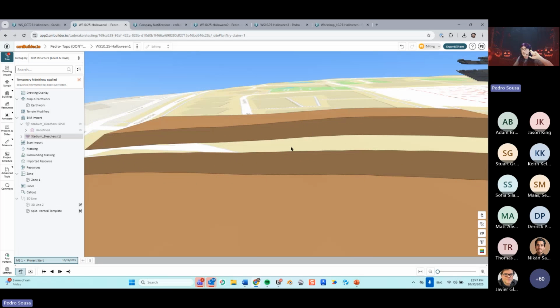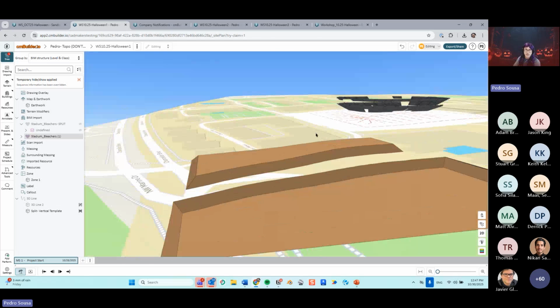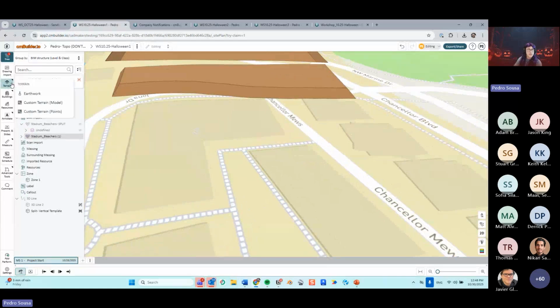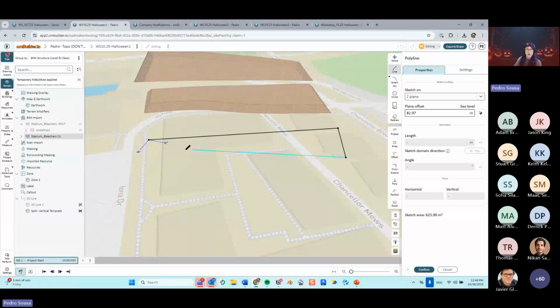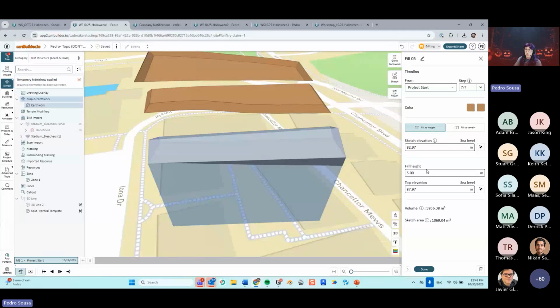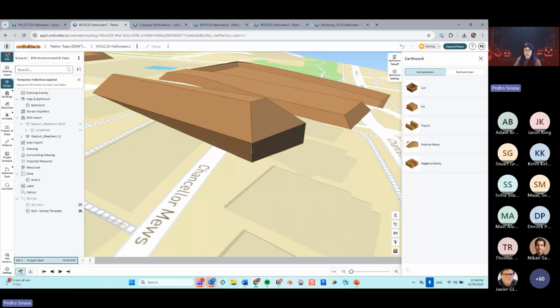a constant height of 3 meters or something like that for the whole thing. So the way to do that would be kind of a quick workaround on the tool. Basically, we would do a fill, and I'm going to do my fill the way that I want over here with the shape that I want. And that fill, I'm going to create with a height that is higher than what you want. If you want your fill to be 3 meters high, you can create the fill higher than that. So I'm going to create my fill higher, say 6 meters over here. And as you can see, this fill is straight from this point onwards.